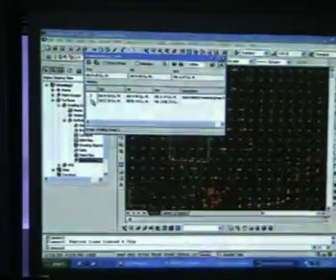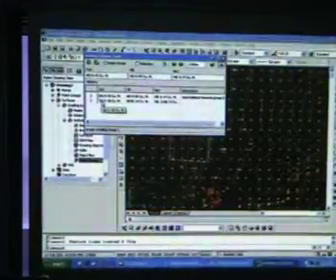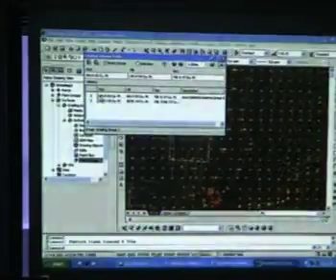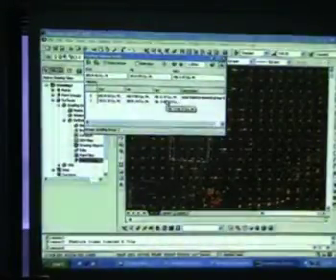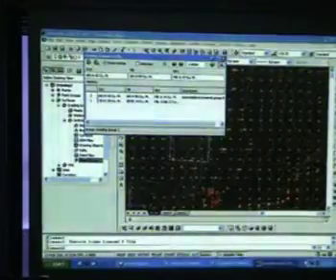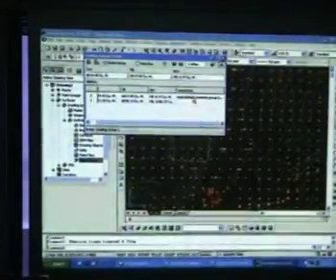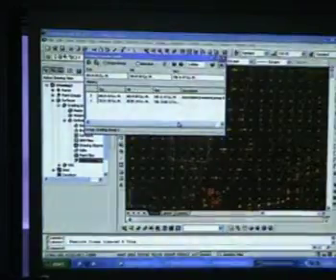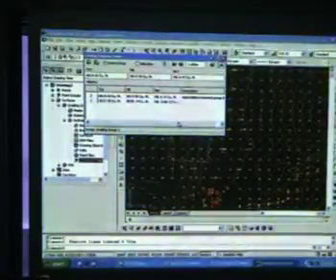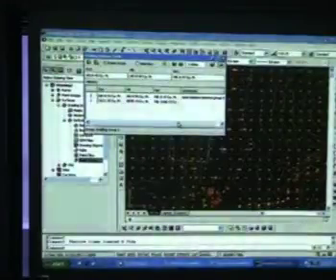You can see this is the history. That means initially, the first time it was this much. After that, they balanced it. We got this much of cut, this much of fill. Our net volume is maybe 1.47 cubic meters. And it even explains to you what happened. See, description: auto balance lower group. So this is where you can balance the volume, raise or lower the platform.